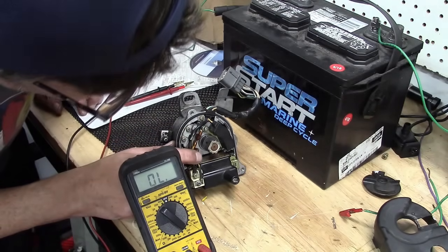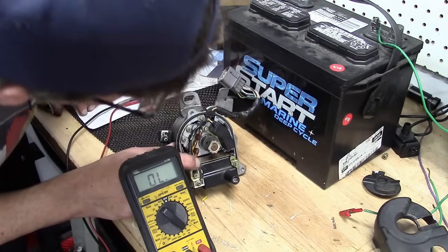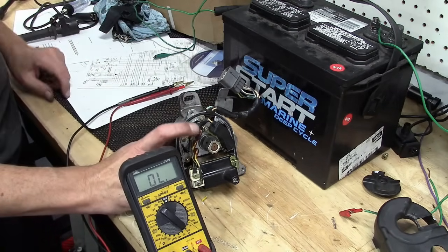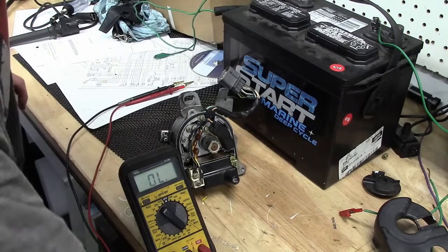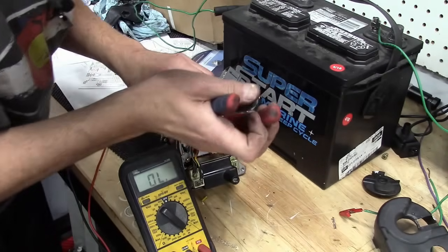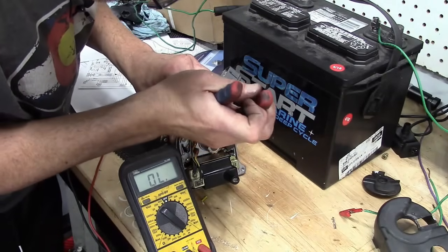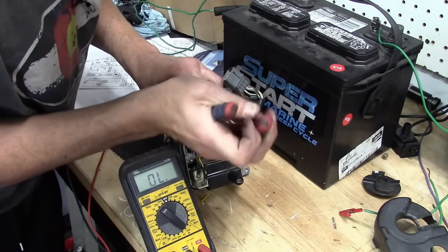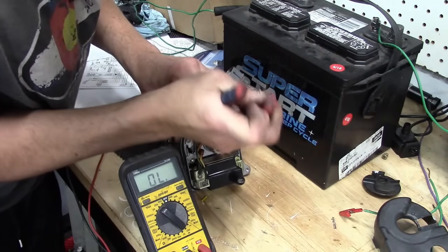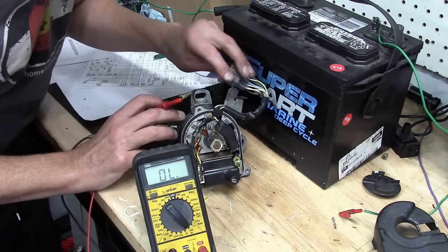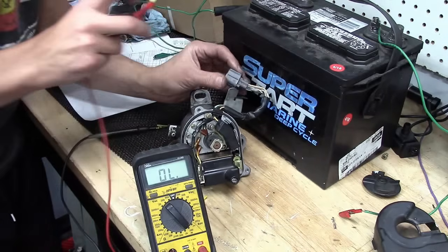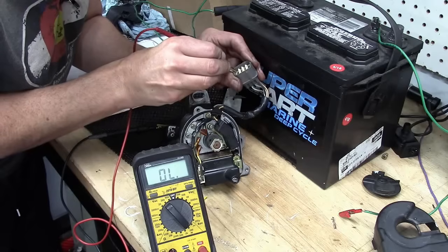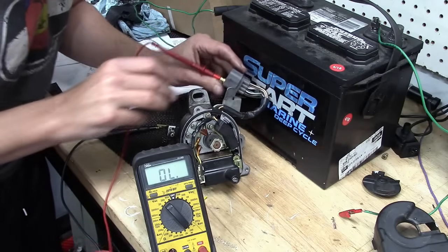So that is going to be our input on this side. This looks like a ground control or something over here, but whatever the case is, this here is our ignition input. So I want to take that wire out, or at least lift it up enough that I can measure continuity there with our ignition input that we know is reaching the distributor. All right, we are going to test that the same way. We've got one wire up here. That's our white with green. That was our ignition input.